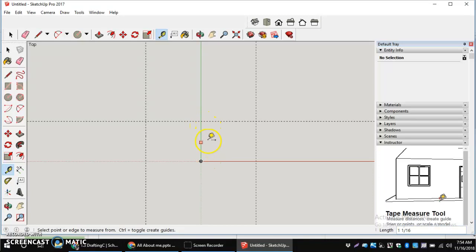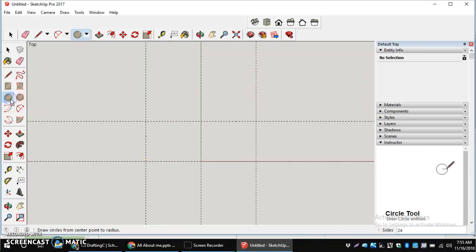Now, the next thing is sometimes, for some reason, our axes or our guidelines aren't live. In order to get them that way, all you have to do is use your last guideline, click and drag down, and make a few more guidelines, and that will for sure then allow them to be active. Some software, like mine, was showing up as intersection there, but on some computers it just doesn't go live. I'm not sure why.